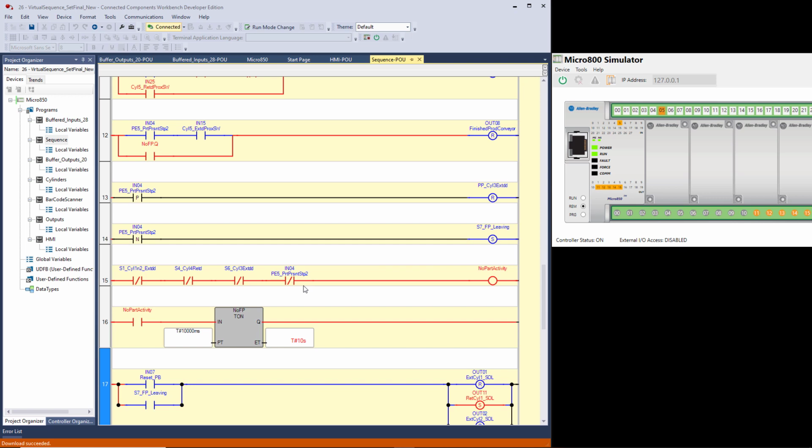That's probably the only complex code in this logic, is these two instructions if you're not familiar with one. And what we did with other platforms is we would use a true if on, then a one shot. True if off, then a one shot. Therefore, the rung would be true when this instruction went true for one program scan.